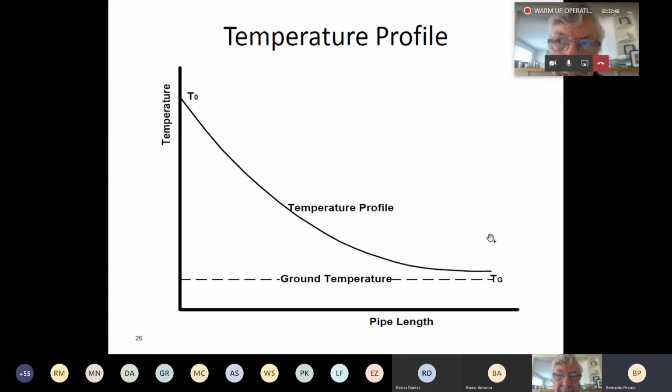Whereas a centrifugal compressor is used on the transmission side of things, and only after we've gotten rid of all the liquids, because liquid droplets would be destructive to the impellers of a centrifugal compressor. So can we go to 28?